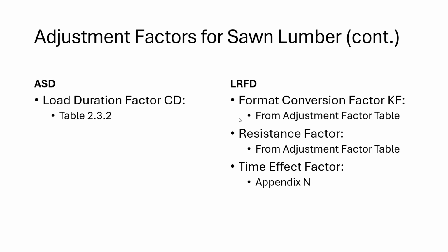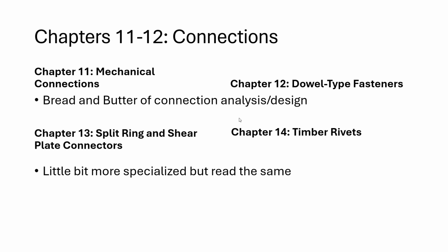I'm going to have 90% of this bending value, and I don't have to do anything else. So that is something to look at. I learned LRFD in school up until I got to my wood design class, and then I learned and actually applied ASD principles. And I will say, I think it's much easier.